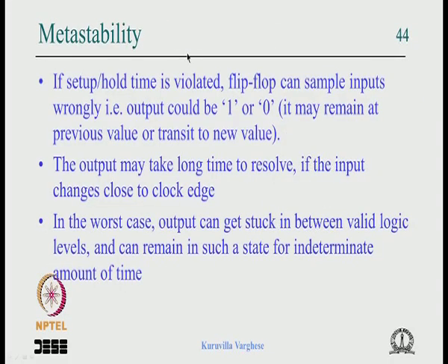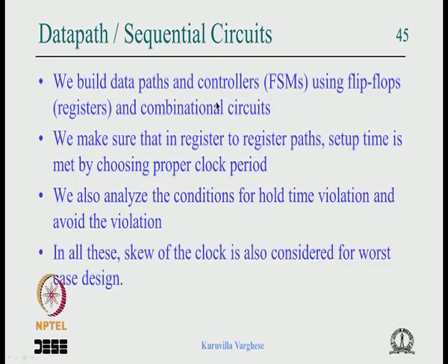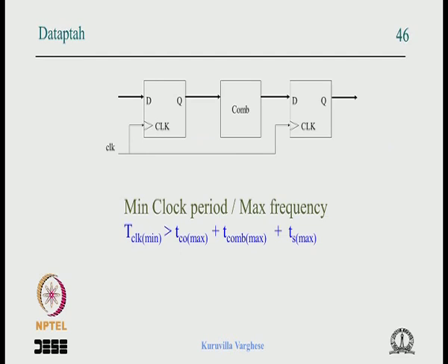So let us come to the effect of it. In a sequential circuit or in a data path, we take care of all these. We choose the proper clock period to meet the setup time. We analyze the effect of the skew, we analyze the effect of hold time, and the skew effect on both. We have not discussed that in our lectures, but we will be doing that when I take up the FPGA part of the course.